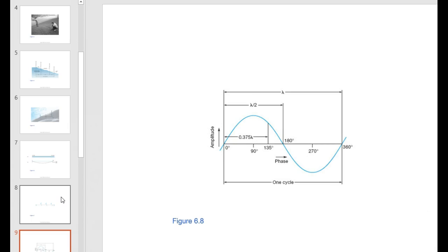So that means that the time for it to return is incredibly short. And you would need to have a super accurate clock that really doesn't exist in this universe in order to measure 1/100th of a foot, which is the level of accuracy that we're looking for with survey quality instruments.